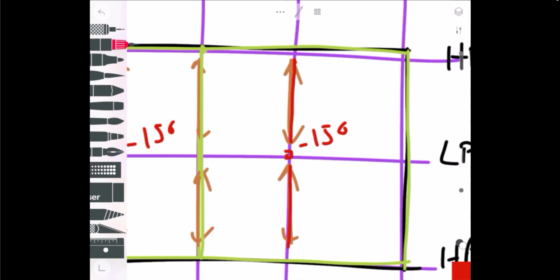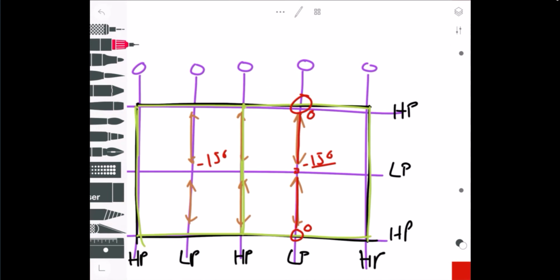So what that means is this is going to be a zero height at this end, so the beam's going to attach at a high point on these two ends, and then we're just going to lower it down 150 millimeters where it attaches to the column. Okay, and the joists can just span across, there's nothing special with the joists, they just make up for that